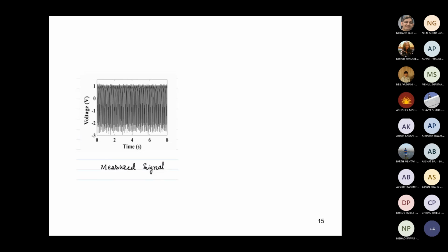You attach a vibration measuring device to that shaper machine, take the readings, read them out on the computer, and then feed it to the FFT analyzer or to MATLAB and do the fast Fourier transformation on this. So what will I get?